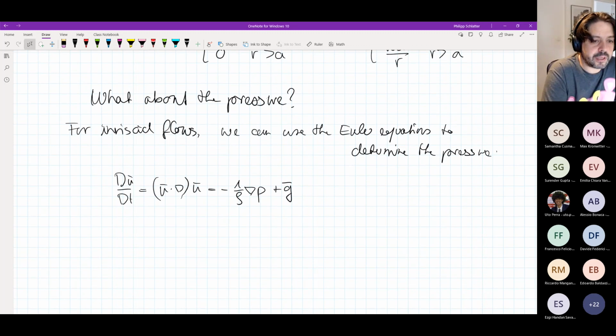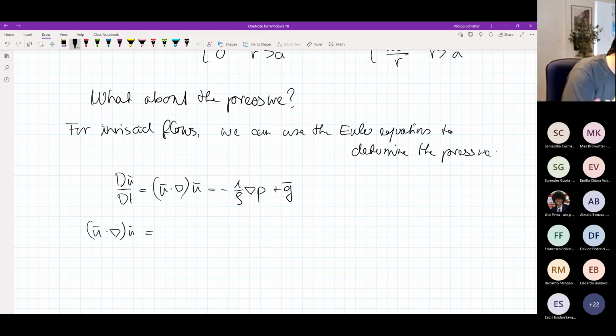Now, if I look at this equation, actually, I don't need to look at a specific direction. I just start to write down these different terms as what they really are for concentric streamlines. I have the first term, u times nabla times u. This essentially is now, for the velocity field that we have, because we only have the u theta component left, u theta divided by r, d theta times u theta. And this is in the direction of e theta.